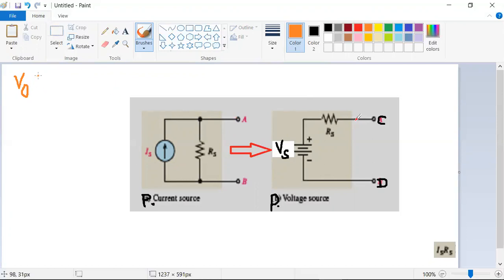For the flow of current, some particular path needs to be present, but for finding the voltage, a path is not required. If you have a DMM, you can measure the voltage directly. But for measuring current, you require a load or closed path. Voltage can always be measured in open circuit itself, and the drop can be measured through the resistance itself. Open circuit voltage across AB, right?